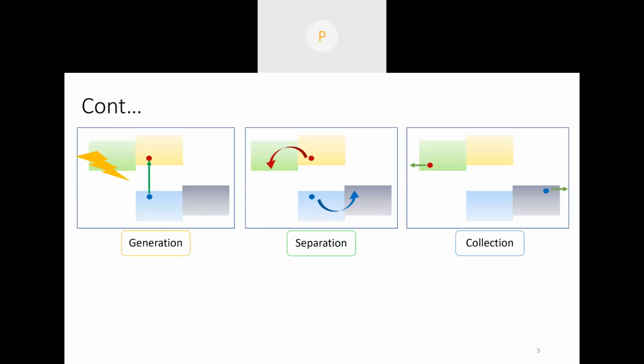Yeah, so how a solar cell works. So these middle layers you have seen in the previous slide also. So firstly, your solar radiation is absorbed by the semiconducting material and your electron will be excited to the higher energy state, leaving behind a hole or a vacancy in the valence band. This you all might have studied. So what happens is then this electron, which is in the high energy state, can come back again to the valence band after some time.